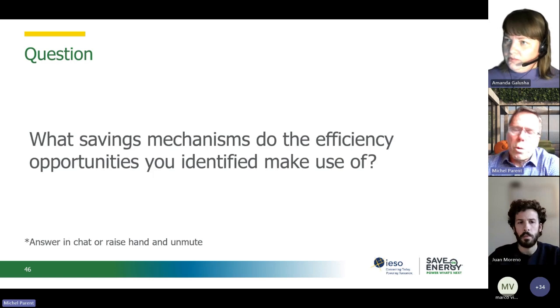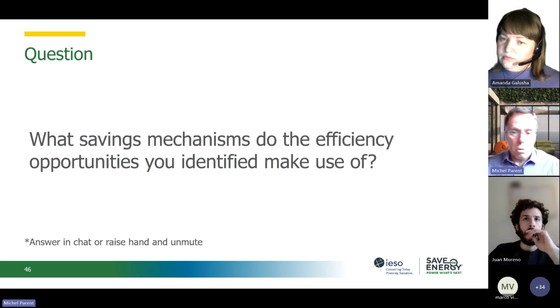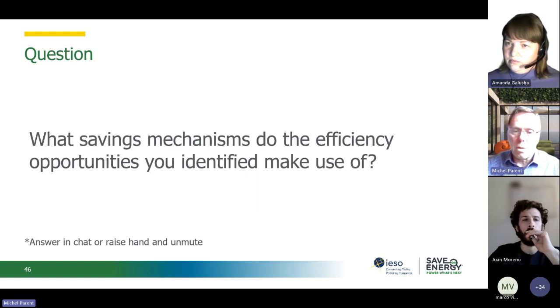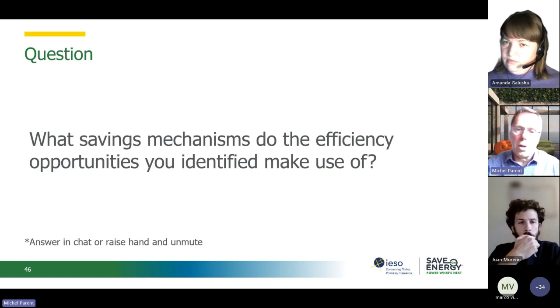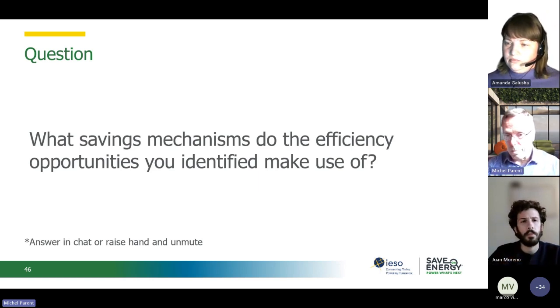So the unoccupied mode shutdown, typically, if you've got zone level heating, you don't even have to worry. Your BAS will just shut it down, obviously. The only time you have to be careful about unoccupied mode shutdown is if the system that you're shutting down is actually providing heating to the building. Usually cooling is not an issue. People will stop it and the building will warm up and you just early start the next morning. So if your system provides the main heating source for the building, then your BAS could take over without a VFD, but it would lead to restarts. So you would have more stop and go for your system.